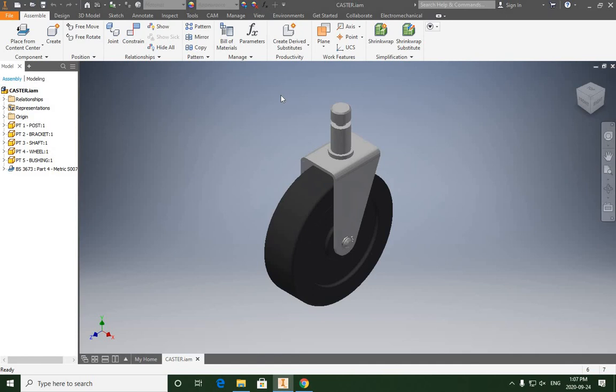So try this, right? Make sure you get your parts assembled correctly. Make sure you bring the parts in correct ascending order like you see here. This is important because this is going to make sure our parts list in our drawing file is set up in correct ascending numerical order. So that means that part 6, the retaining ring, will naturally be at the end.